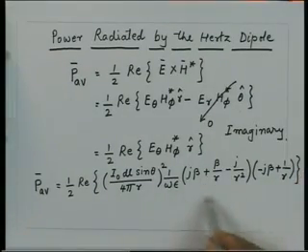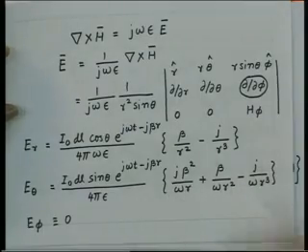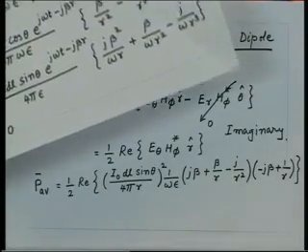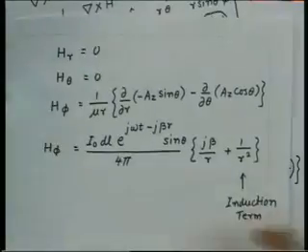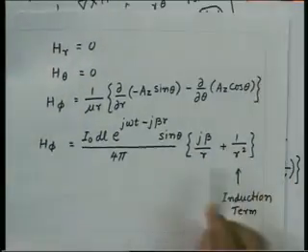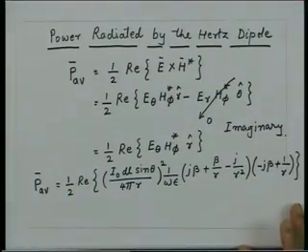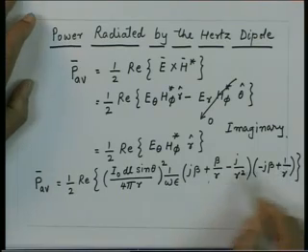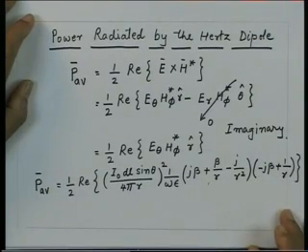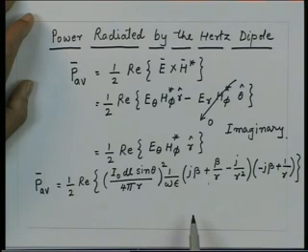So, you see this term is essentially coming from the electric field which is this term, whereas this term will be coming from here, and we have got a minus sign here because it is H conjugate. So, this becomes minus j beta term. Now, again if I see the terms, the real terms, many of the terms will cancel out. So, only the contribution will come only from these terms, which is j beta and this quantity.